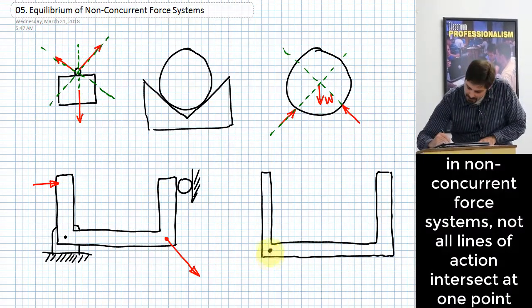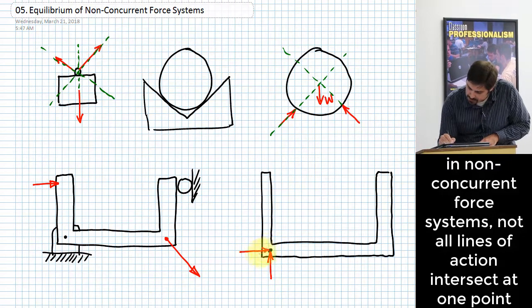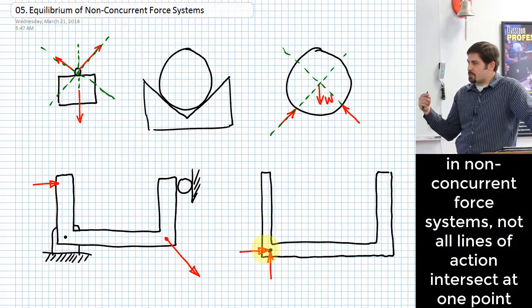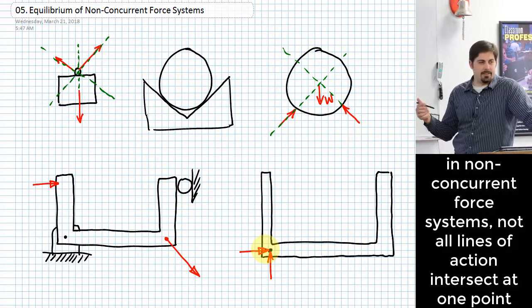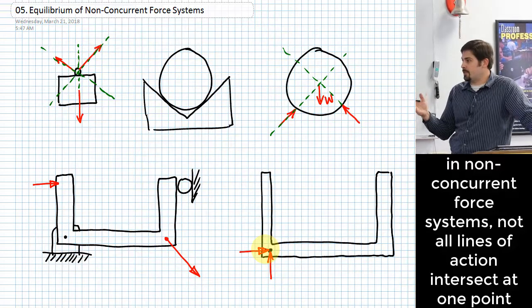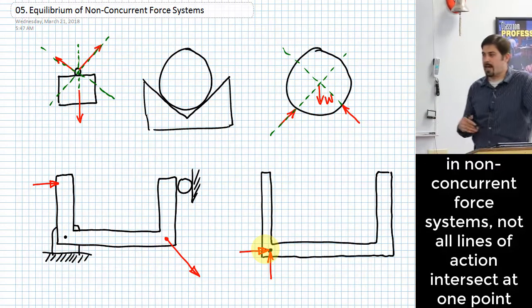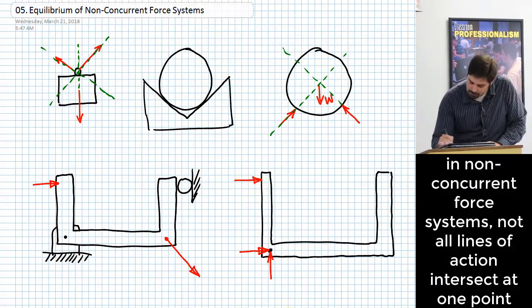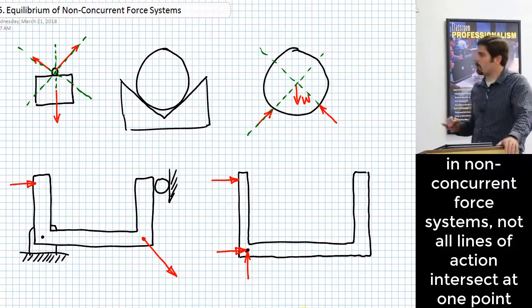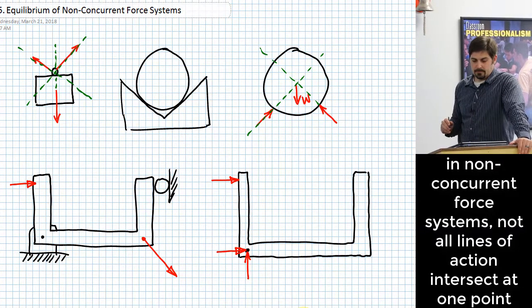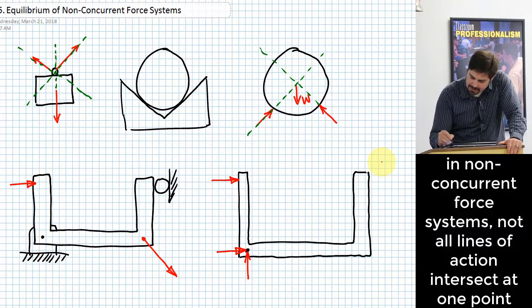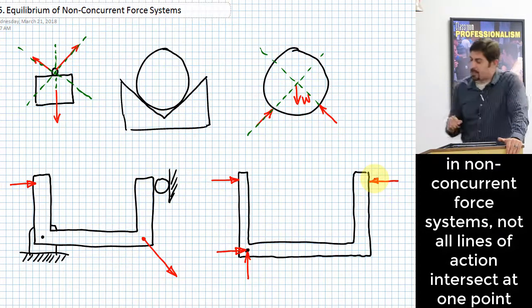Rotational is the one reaction we probably don't have. We have reactions happening vertically and horizontally because these represent forces that we know must exist there if it is not going to be allowed to move in those directions. There have to be forces there that will be whatever value they need to be in order to prevent movement at those locations. That's what we mean by reactions. And then we'll also have a force up here. What does that roller do? How does a roller behave? Parallel to the surface it rolls against, that's where the action happens. Actually, the force happens perpendicular to the surface that it rolls against.